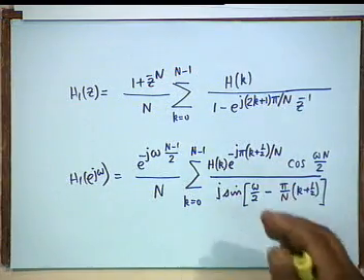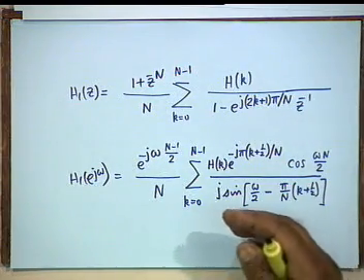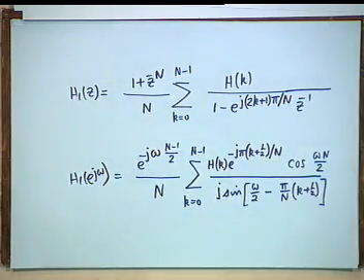Now, let us look at an example. Type 1 and type 2 designs of frequency sampling guarantee linear phase to start with. If you do not want linear phase, then you do not have to bother about it, while things become simpler as well as tougher. In linear phase you have to compute half the number of terms. If it is non-linear phase, then you have to compute all the terms, but you may be able to do it with less number of terms.